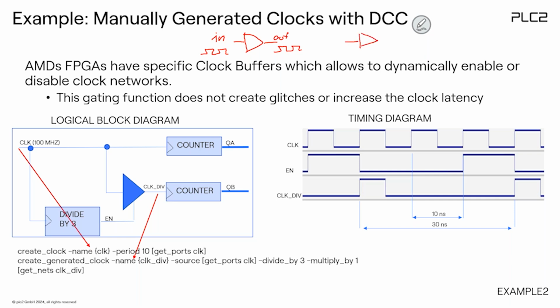So in this case, you have another clock buffer that looks like this. It looks like a tri-state buffer, but it's not. So this is again the in, this is the out, and this might be the enable. For example, if this is the in, and then the enable is maybe here, something like this, then the out would look like this. So you decimated the clock. In this case, it's 1, 2, 3, 4 by 4, and this is exactly this guy here. That is an internal, very special clock buffer called BUFGCE.